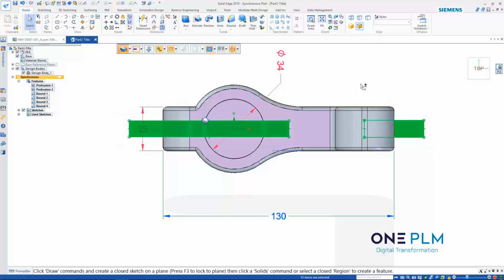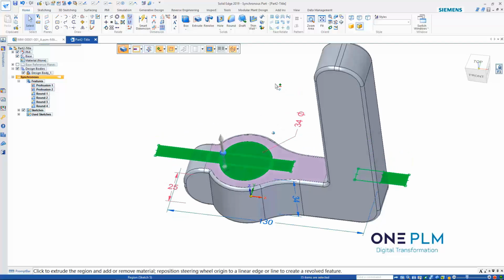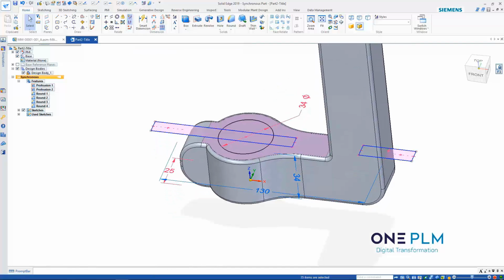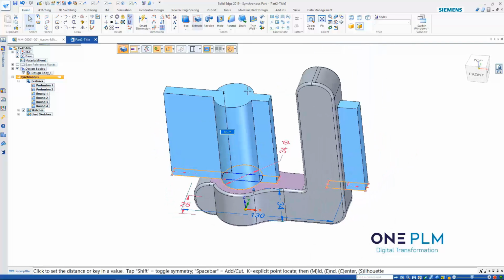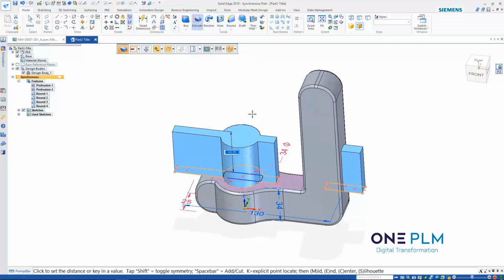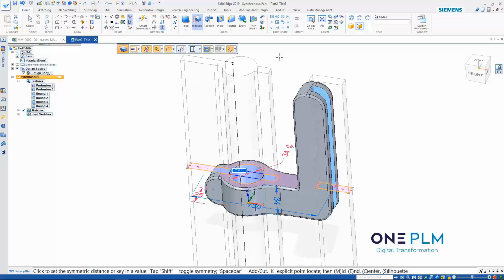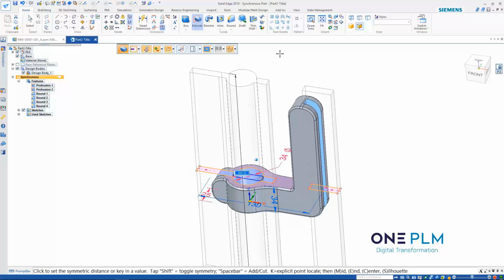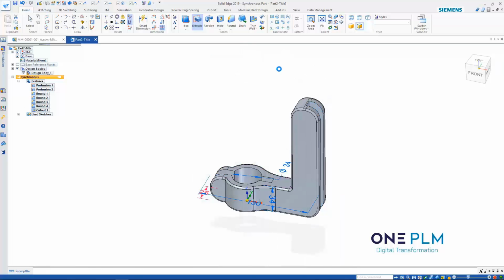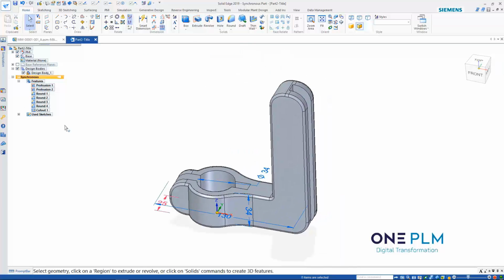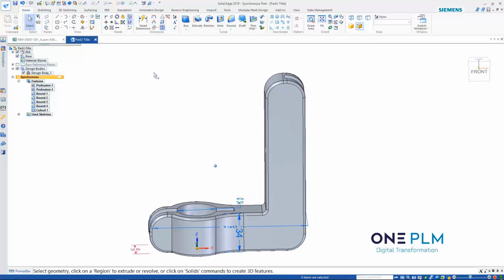Then what I'm going to do, I'm going to select those regions. And I'm just going to use Control, same standard window shortcuts to add those 2 extra regions that I've got. And then I want to drag. So when I do it that way, I can use the standard keyboard shortcut Shift, because I'm going to change that. As soon as I do that, it realises straight away how I want that to go. So I'm just going to drag that all the way through, and that's then going to put cuts through top and bottom on there. Okay, so now we've got a cutout in there.